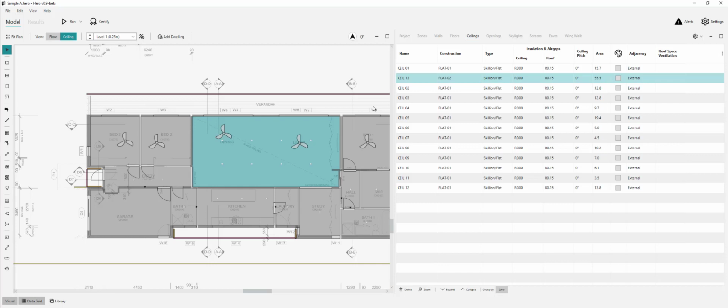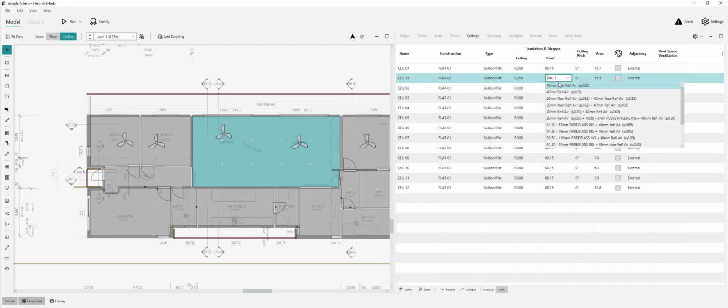And we know it has 2.5 ceiling insulation, and its roof insulation is a 1.3 blanket with a 0.05 reflective, that's the emissivity, reflective airspace value. So that's going to be the most appropriate for us. There's non-reflective options there, and there's even blankets installed with reflective finish facing up. So here we're reading it from the external side in. It's going to be this is our blanket.